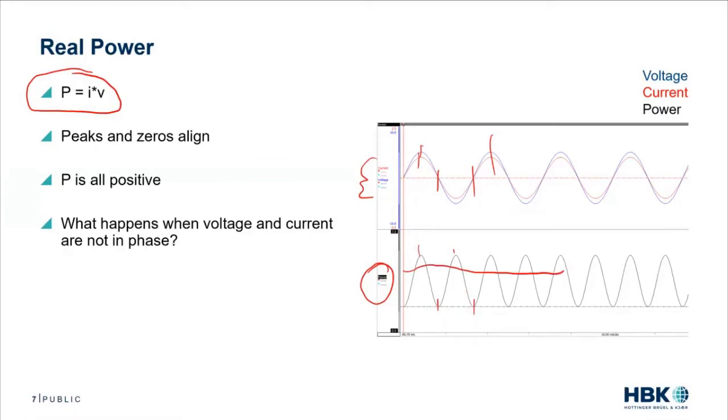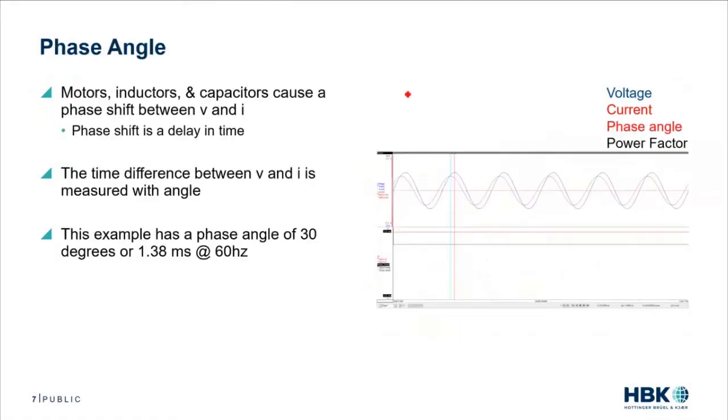This is going to be in contrast to what we're going to see in a moment, because as many of us know, this voltage and this current are not always perfectly aligned. We introduce what we call a phase shift. And in my next slide here, I've introduced a 30-degree phase shift to my voltage and current. So same exact waveforms, except I've delayed voltage in time by 30 degrees.